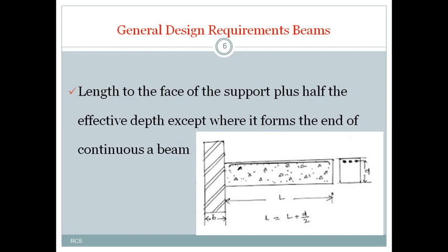As we know, for a singly reinforced cantilever beam, we have to provide the reinforcement in the tension zone. For this cantilever beam, the tension zone will occur above the neutral axis, as the topmost fibers of the beam are subjected to tensile force when it is subjected to vertical loading. So the cross section will be like this.